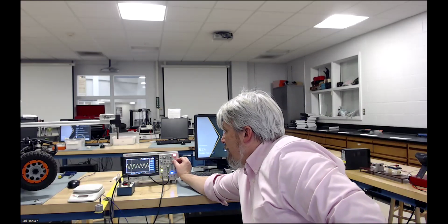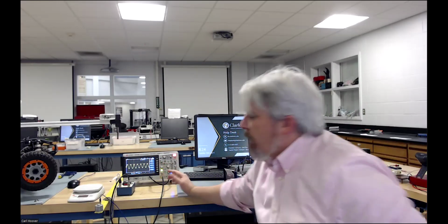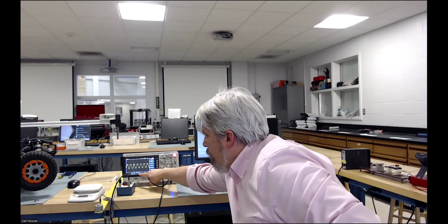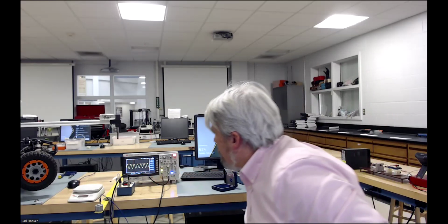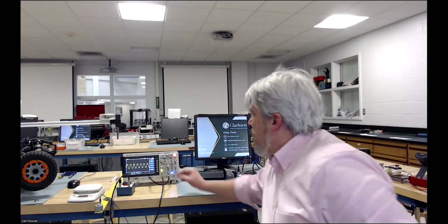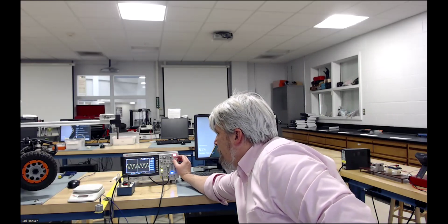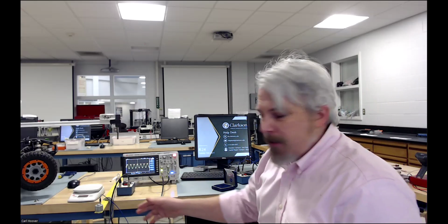and with that I can go through and pick off voltage peaks. So right now I'm finding a peak here. I'm going to note the amplitude here, 153.92, and then I'll go and find the next peak. It's slightly lower, 147 millivolts, which means it's decay. That decay will be different depending on the length of the beam and the masses of the beam.